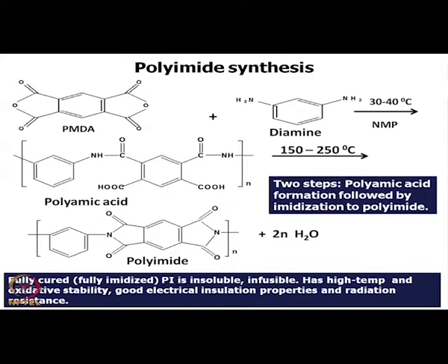To overcome that problem, people have developed this polyamic acid intermediate precursor step to form this polyimide, but one cannot avoid the use of this organic solvent. This is a highly polar, aprotic solvent, and it is used for making this polyimide in the laboratory or even industrially. So, whatever device or object is to be prepared should be prepared with the help of this polyamic acid. Say, if one wants to make a polyimide film, that polyimide film can be made through this polyamic acid.